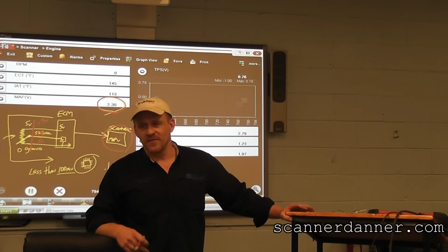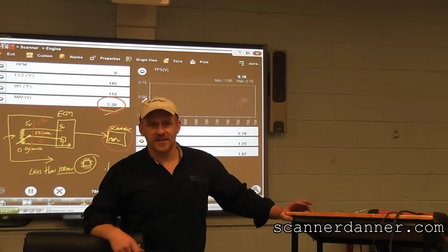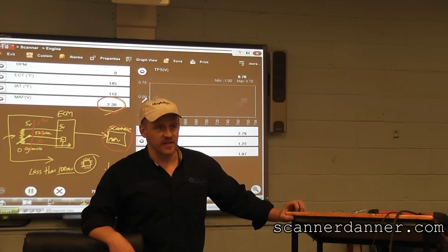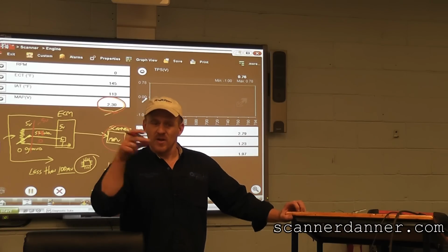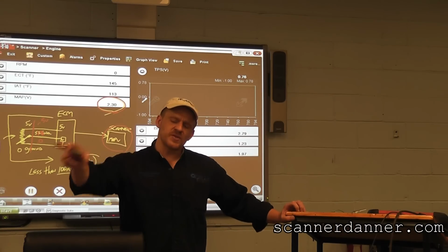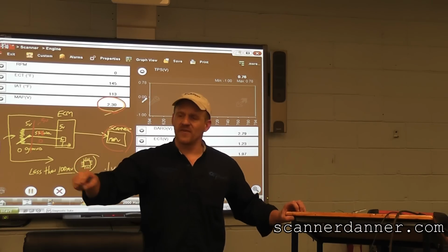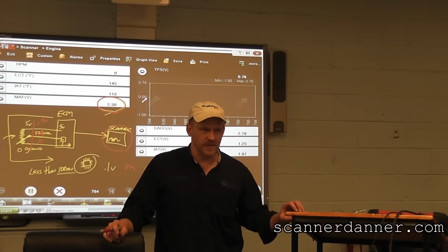Another one, I have a chapter in, I'm not going to do it right now. It's called substituted values. I have a whole chapter in my book designated to substituted values. This is things that can throw us off in the future. Sometimes a computer throws in a default value that it knows there's a fault in the circuit and is using a default value and will not change that value no matter what you're doing to the signal circuit.